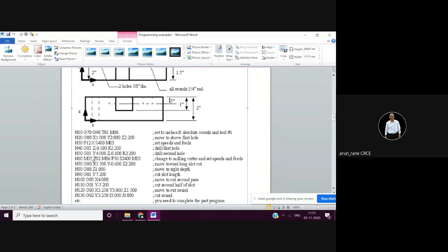That is, you are changing the tool, and that will happen because, as I told, the CNC machine reads the complete block and only then executes it. So this sequence or order is not important. You can have Z here, you can have G00 at the end, it doesn't matter. It reads the complete block till it finds the dot or star symbol, that is the end of block symbol, and it continuously reads until it finds the end of block symbol.